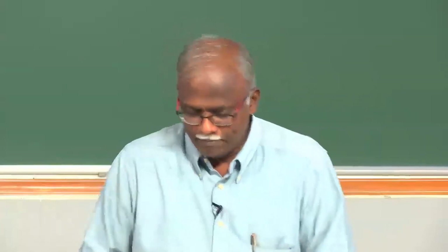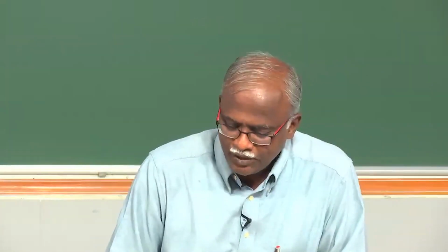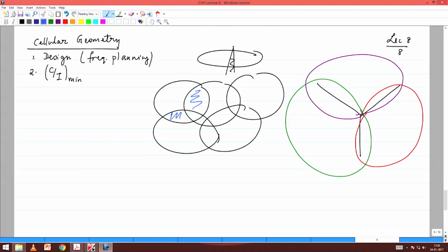In terms of cell planning, one of the things that would be problematic is that there are so many areas that are overlapped by two cells, and then there are some which are overlapped by multiple cells. Those are problematic areas, in the sense that now, to which cell do I assign that user? It always becomes a confusion. So preferably I would like to have non-overlapping cells, so that I can then design my system. Again, in practice it's going to look like this, but when I design my system on paper, I can then talk about capacity per cell, because that is very, very important. So maybe add a third item: I'm also interested in the capacity that we will achieve.